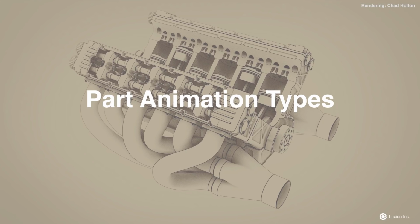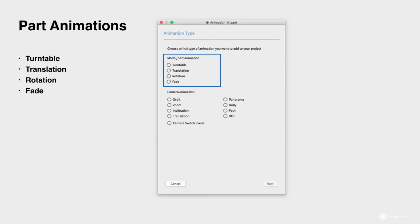Now, part animation types. These are the actual options we have within KeyShot when we choose to animate a part. And these are the ones that we are going to be using to build our overall animations today. So part animations include 4 simple animations. That is a turntable, translation, rotation, and fade. And you see these when you click the animation wizard. It launches the animation wizard, which is a dialog box that gives you options to choose either a model or part animation or a camera animation.